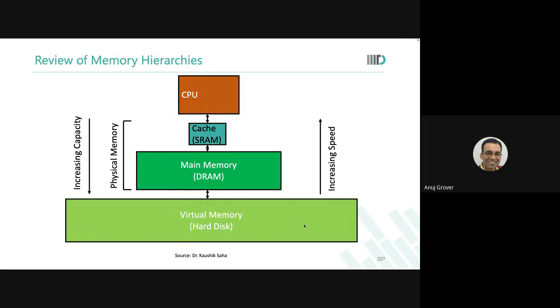Instead of a 1K cross 32 memory, if I ask you to make a 2K cross 64 memory, R and C both will increase. Performance is going to go bad. So I also need larger memories. That is another reason why we now have a hierarchy of caches, L1, L2, L3.